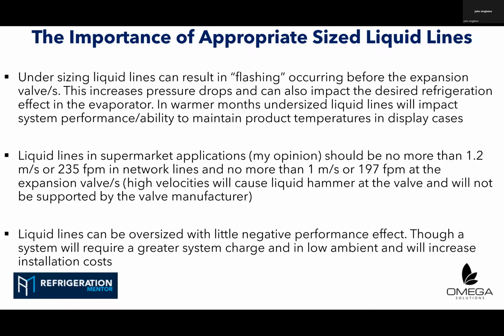So yeah, that could be one of the reasons. We have lots of, I think every system I pretty much worked on is hot gas. And yeah, you always want to have it two sizes up for the liquid, but I think this was more of a small condensing unit with 4 or 5 cases, electric defrost. Yeah. And then, I understand what you're saying there, John. Thank you.